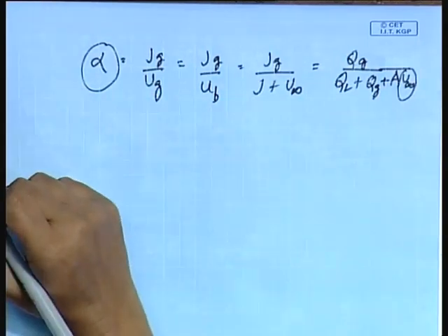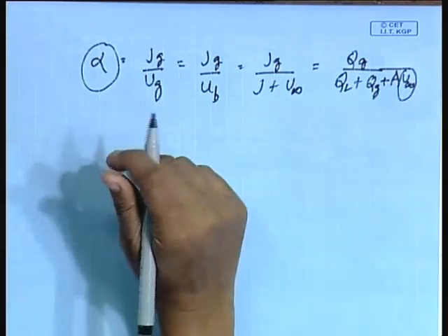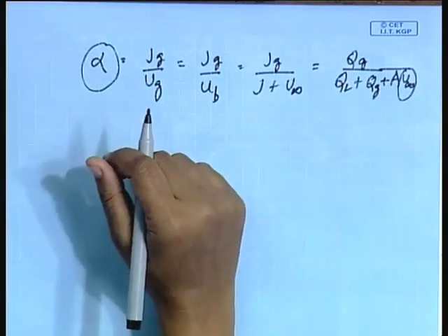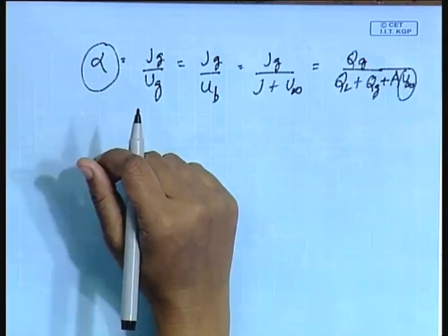Okay. Now, what are the different methods of finding out u infinity? In order to find out u infinity, remember that it is the bubble rise velocity in an infinite medium, I am very sorry, it is the bubble rise velocity in a stationary liquid. Why does the bubble rise? Due to its buoyancy. So, the interaction of the buoyant force with the other prevalent forces should give us the measure of how to find out u infinity, isn't it?